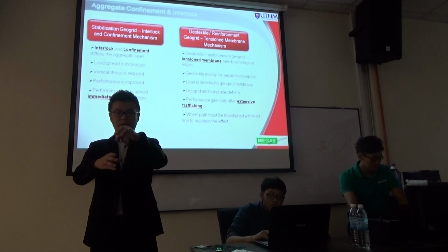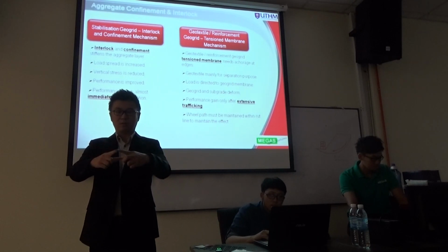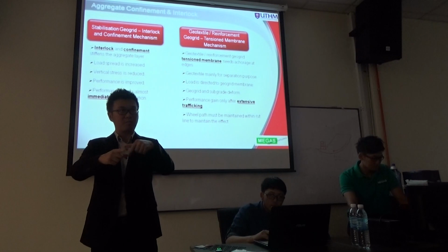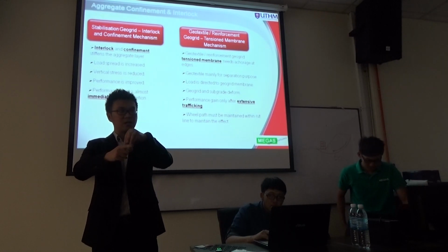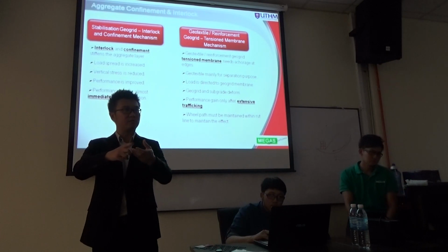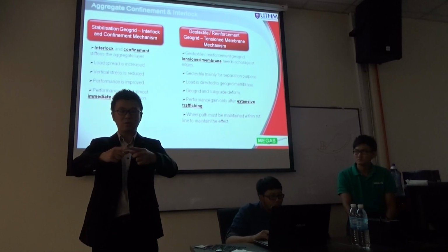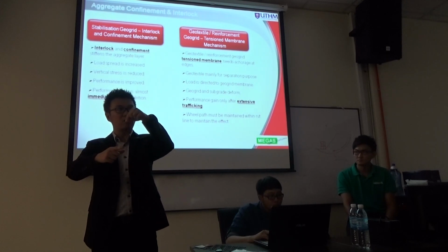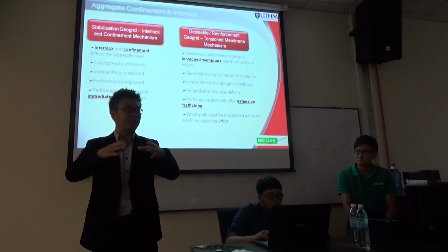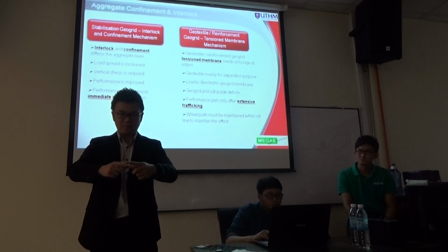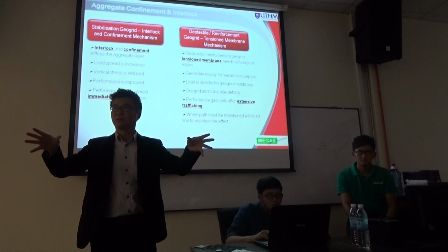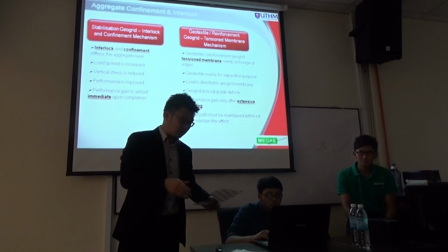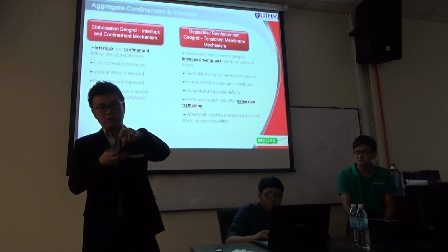So why can it form the pyramid on top of it? Because the bottom balls are confined by the triangular rack, whereas the top ones are interlocked to each other because the bottom don't move. Okay? The balls at the bottom don't move. So you can apply a small load on top of it, it won't collapse, the pyramid will still remain. But if you take up the rack, the whole thing will spread. So the similar concept here is called the interlocking, so we use that concept over here.